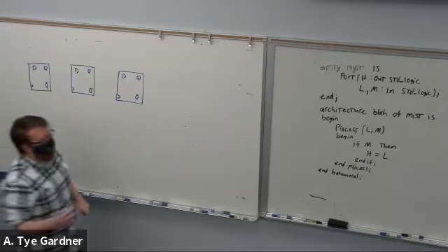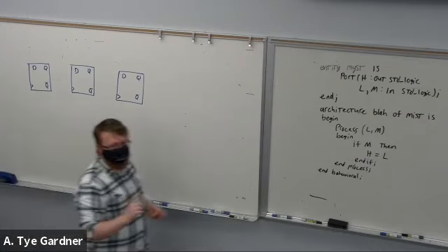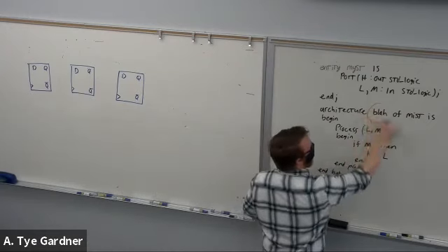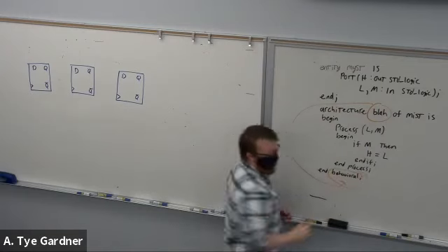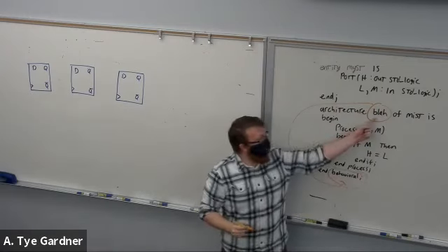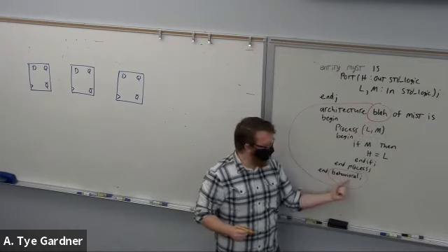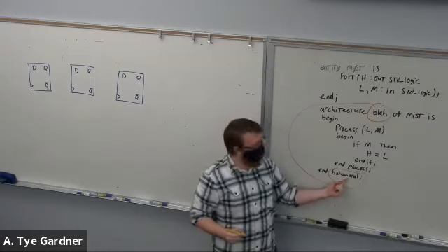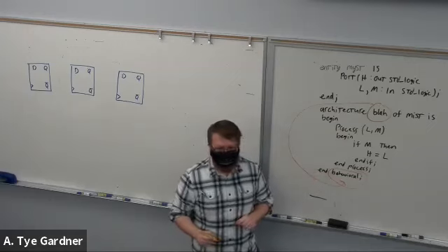All right, so let's start yelling them out. You name your architecture blah, and then end behavioral. Yep. So blah is an acceptable name of the architecture, but I would have to have blah down here. The fact that they don't match is exactly the problem.